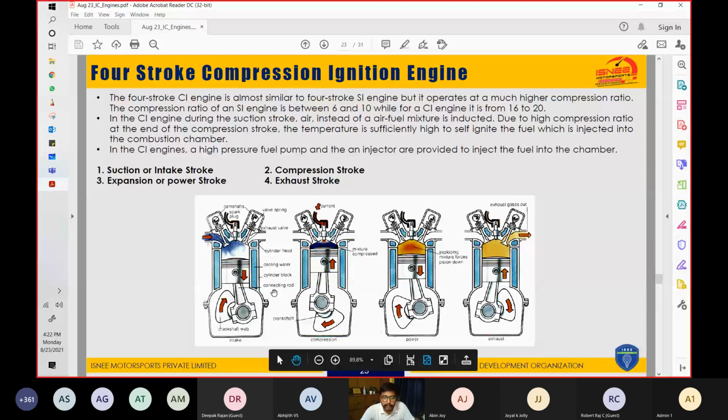Though the cycles or the processes or the strokes are the same in here also and in there also. There were 4 strokes in the spark ignition. There are 4 strokes in the compression ignition. There is only one change. That change is, first, through the inlet, air comes in. So suction of air is done, and in place of the spark, there is an injector over here. So first, air is coming in the first stroke, suction of air happens, and then in the compression stroke, this